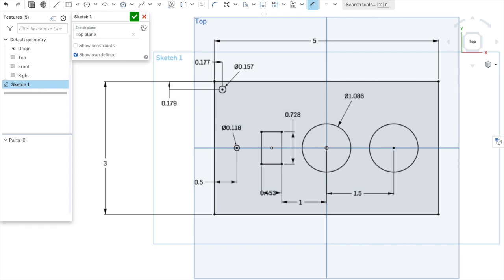Instead of making those other 3 circles manually, I'm just going to use a tool called Mirror, which lets me take advantage of symmetry. So the Mirror tool, when you first click it, will ask you for a line. I'm going to reflect that circle across this middle line. Now I'm going to take the tool and use it again across the other axis. This way I can create these very, very quickly and very easily.